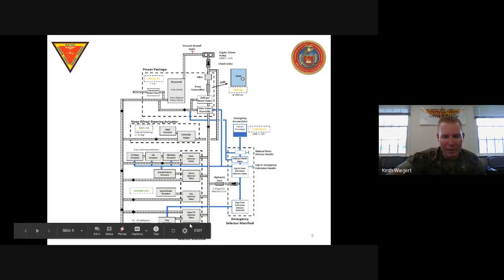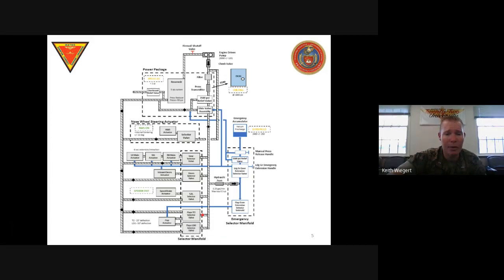All right, dropping down to the flaps, right? So the flaps are going to be the only one where they have 2 selector valves, one for flaps takeoff and one for flaps landing, going to the single actuator because it's only one rod that's going to connect to your flaps that are going to deflect it, right? Takeoff flaps are going to deflect down to 23 degrees, right? And then landing flaps are going to deflect all the way down to 50 degrees. So that's worth knowing there.